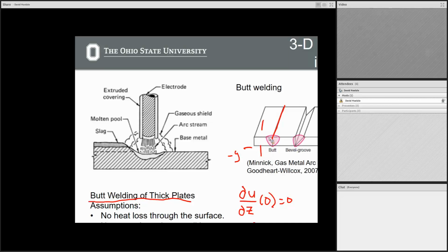If we do not have an infinite plate, if we're welding something that's pretty small, this could be a large amplifier of temperature, right? Imagine now that this is even half the size. All the heat that goes in here really has to stay in that part. It's just going to get hotter and hotter the more you weld it. So that could be a continual worry.